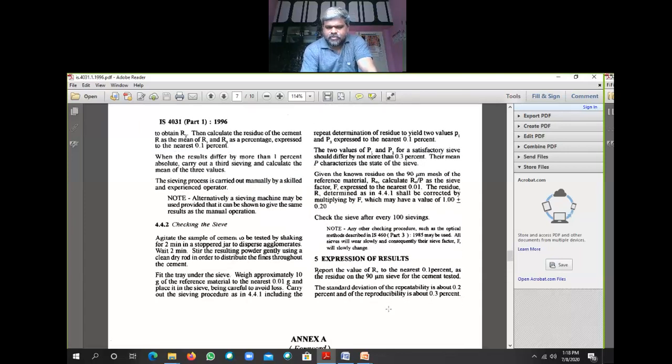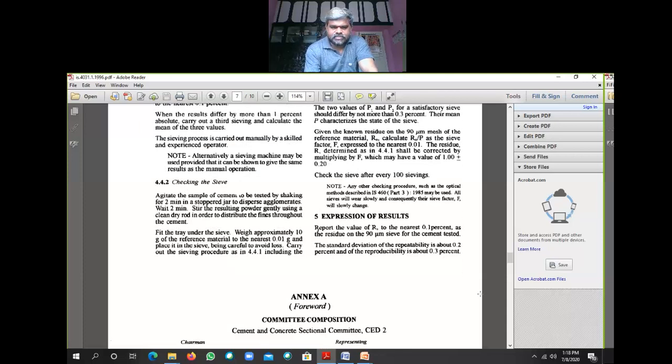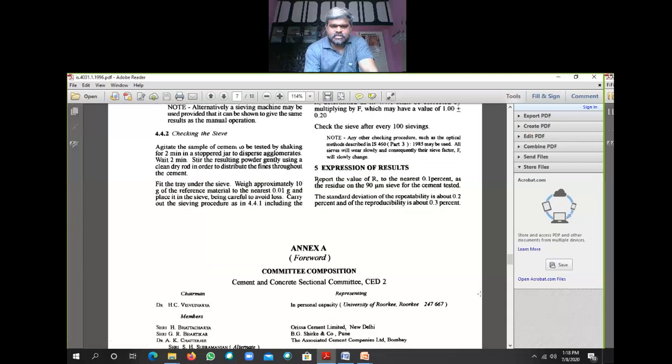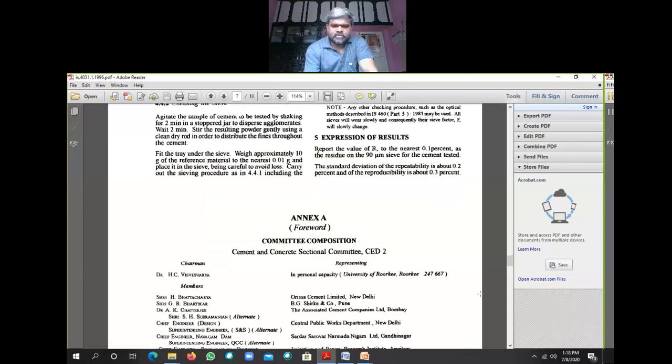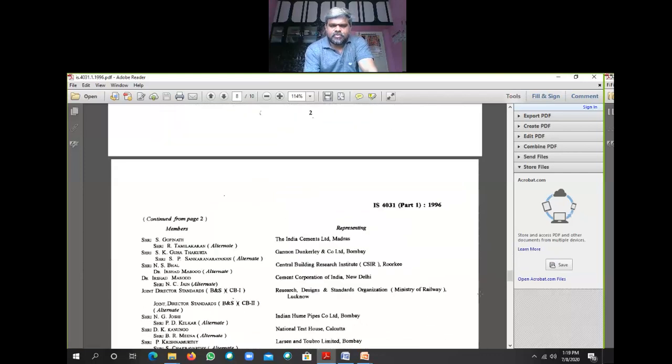Report the value of residue to the nearest 0.1% as the residue on the IS 90 micron sieve of the cement tested, with a repeatability standard deviation of about 0.2 to 0.3%. So this is simply the fineness of cement, right? It should not be more than 10%.